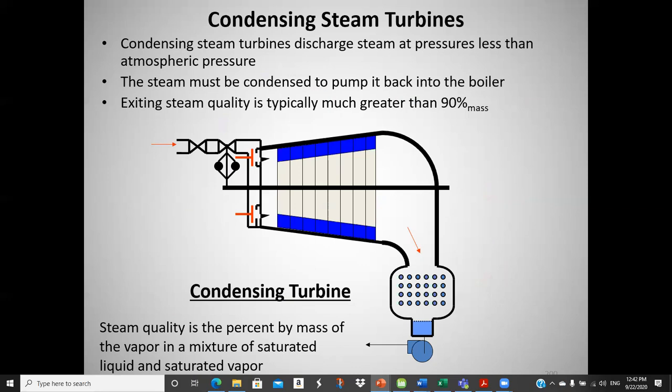Condensing, we simply pull the pressure down as low as possible and it'll be two-phase coming out of this. It'll be wet. You'll have 5 to 10% moisture. The rest of it's steam. Again, 1,000, 1,100 BTUs a pound goes to the condenser, just a heat exchanger. It can be an air-cooled condenser. We'd like to do water-cooled because we get lower temperatures, and the lower the temperature, the more efficiency you get out. And so that's probably lake water being pumped through there.